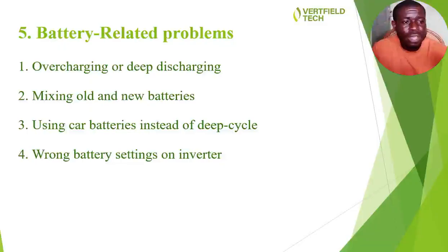But when you decide to drain these batteries to 100%, in most cases for the lithium battery, it becomes very, very difficult to charge them. And so you might end up damaging the cells of your lithium battery. The same thing applies to your lead acid battery. So please, we are advising you to always adhere to the manufacturer's set rules when it comes to the charging and discharging of your solar batteries.